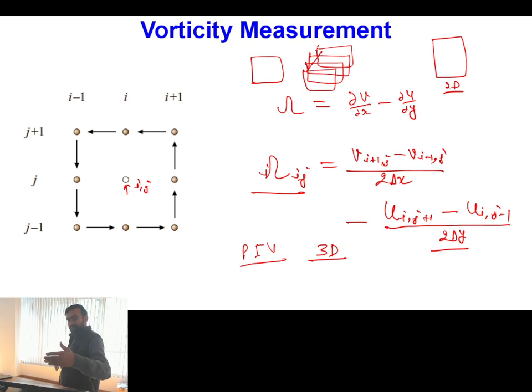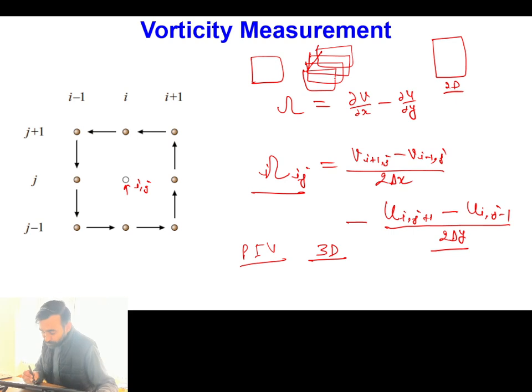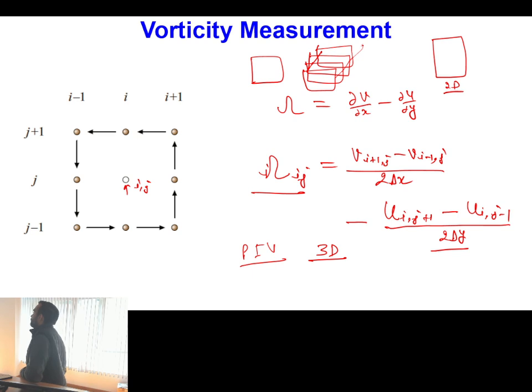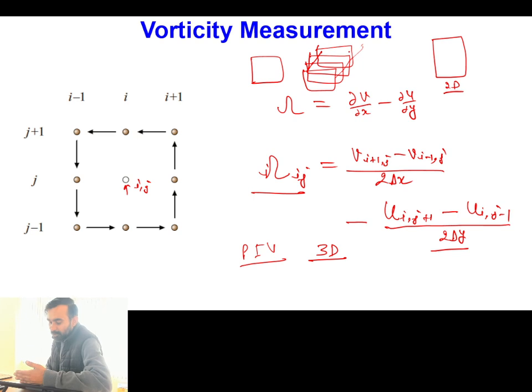So in one plane it will give two consecutive pulses, the next two pulses it will give at some transversely backward location, the third it will give at a more backward location, and these movements will be so fast that almost all the particles will appear as still in the subsequent phase. Because ultimately, whenever we are creating all these pulses, there should not be significant changes in the flow field at the different planes. If you are trying to construct a three-dimensional velocity field and the situation is turbulent flow, this measurement should be simultaneous.